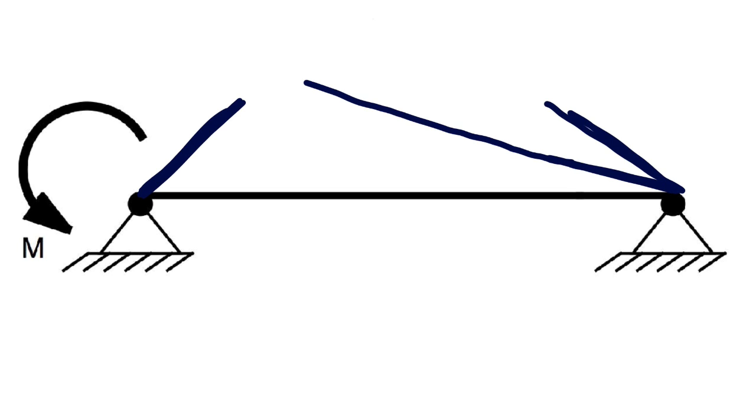We extend this stub on the right and we want to meet with this line from the other side tangentially. We want to have the maximum height to occur at about 42% of the length from the left end, which is the theoretically exact location. Well, we locate the middle and move a little bit to the left. No need to be too precise in a sketch. And we mark the maximum level with a line at about that distance. The height of the maximum is theoretically about 45% of the height of the extended line on the left.